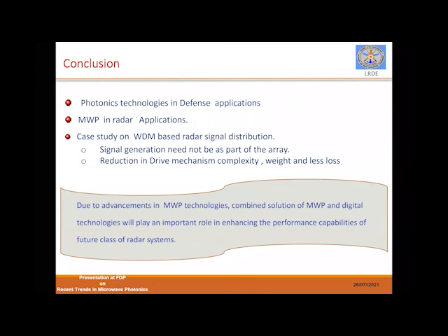Here you should not get confused. Are you talking about multi-mode communication? What I meant was each signal should be converted to one lambda. That is achieved with the help of a laser. Nothing to do with the mode, which can be one, but the wavelength is changed. There is something called multi-mode propagation, like the mode multiplexing technique. I'm talking about the wavelength division multiplexing method. Hope I could convey your query properly. Okay, madam. Thank you.